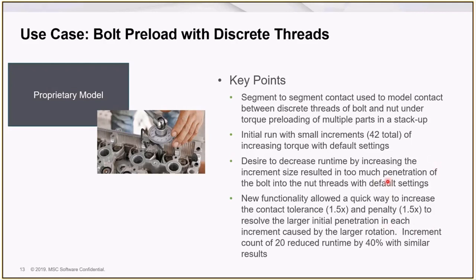But because we actually had too much penetration, if you think about the threads of a bolt turning into the nuts of a thread as you're rotating it, as you're applying the torque, the more you torque it, the more you rotate it, the more penetration that will happen. And so, understanding the mechanics of any problem is very important when you're doing simulation.